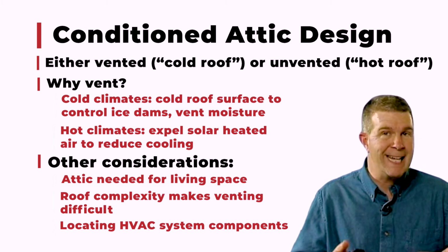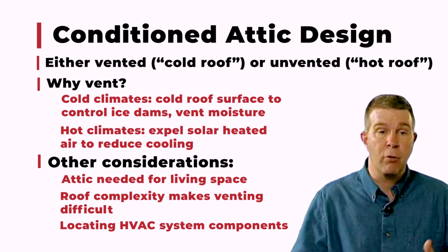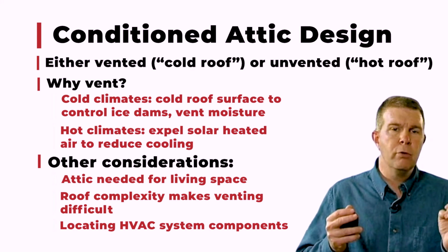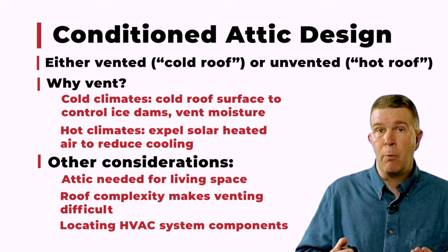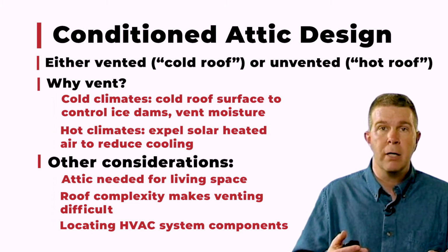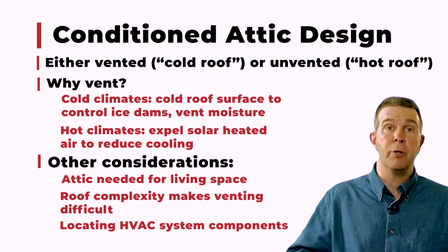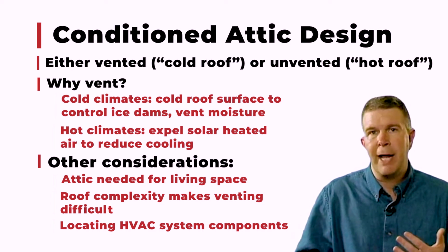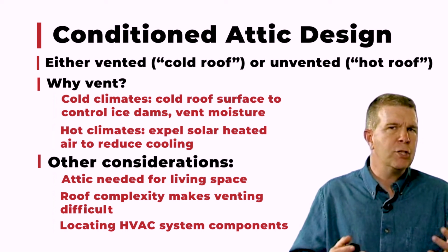The SIP panel takes the insulation out of the ceiling and moves it up into the roof line. And this can be a really good thing for us in a lot of different areas. In cold climates, the cold roof surface is sometimes used to control ice dams. And we do that with a ventilated layer over top of the roof to maintain that cold layer. And that's where the misnomer of hot and cold started to come into play. People thought that when you put the panels up there, you were going to get a hot roof, and somehow that translated to shingle warranty issues and you were going to degrade your roof system. And it's just really not that true.